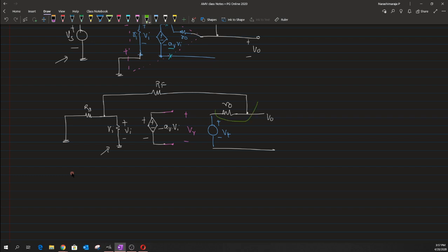You could see that this has been connected through this resistive path. Okay, and this is one of the components that I have, and there is also one more component where this Vi is not only a drop across this resistance Ri, but it is also a parallel combination of Rs and Ri. Okay, so one could use a simple voltage division rule in order to compute the voltage drop of Vi.